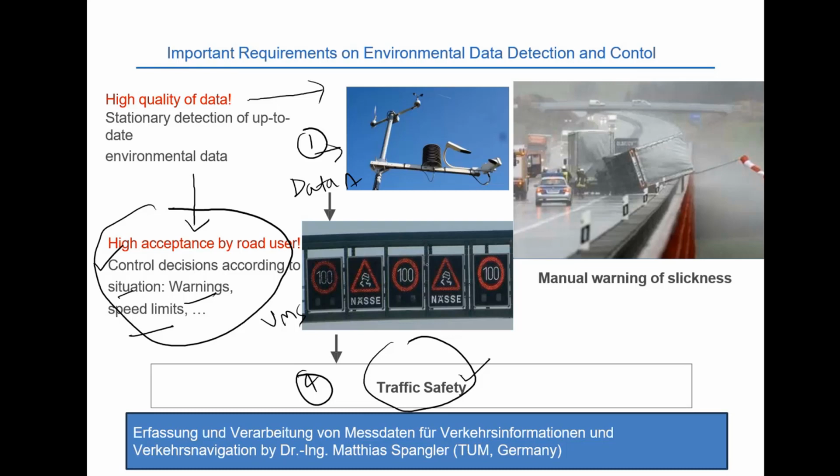So when we detect the state, which we call slackness, or the potential slackness due to the icy condition, or the kind of frozen wet condition of the pavement, by using different surface models, we then initiate the warning regarding that slackness, which could be displayed for the operator or the driver, so that that kind of unplanned or uncertain situation could be avoided.